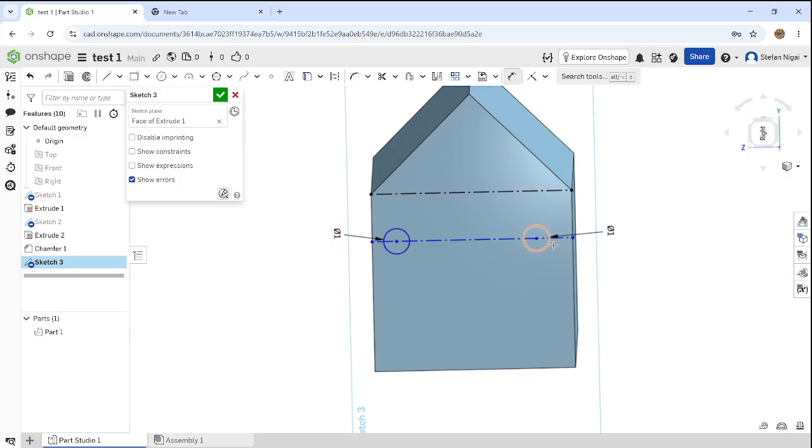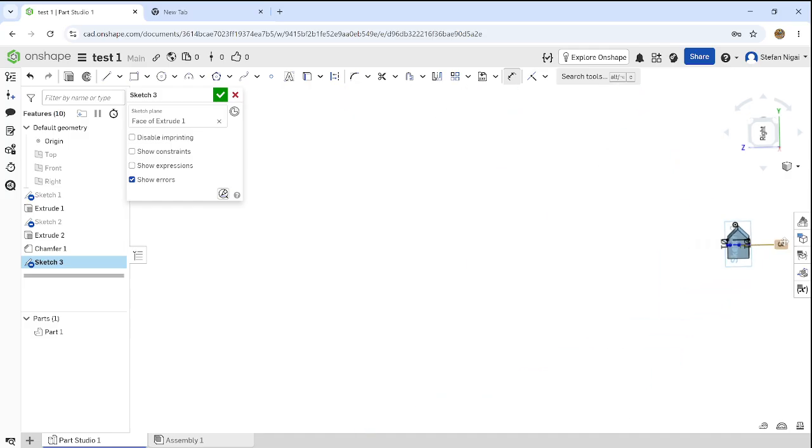And now, of course, you want these circles to be at the exact diameter, like you want it to be more toward the center. You guys are gonna see exactly what I'm gonna do. Okay, I don't know how to speak English. So you're gonna click like this, and now you're gonna select the distance that you want it to be from the other line. That's what I wanted to say. And now we're gonna put it to, let's say, 3 millimeters. Oh my god, no, 3 millimeters is too much. Why is it so far away? Okay, we're just gonna put 1 millimeter away.